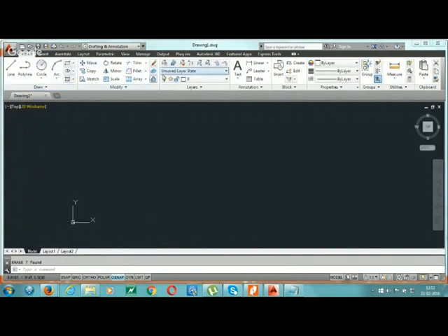Anyway, this is the toolbar for the drawing commands. If we go ahead one by one, you will see line is there, then polyline, then we have the circle and the arc. Likewise, rectangle, ellipse, and hatching are there. So we are drawing the circle in this. I will do this with the help of the direct entry command, not with the coordinate system. The same thing you can do with the coordinate system also.